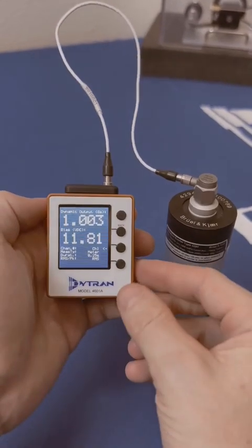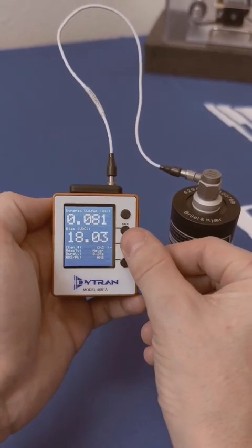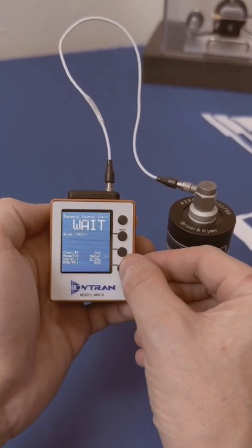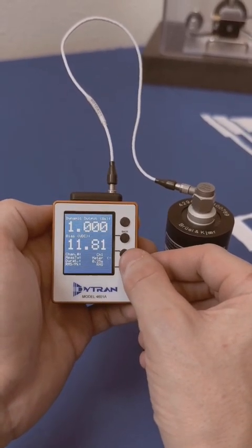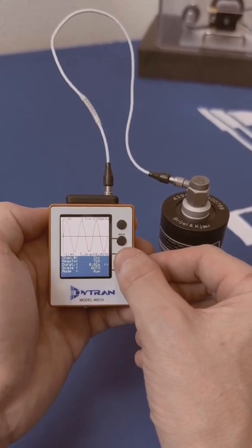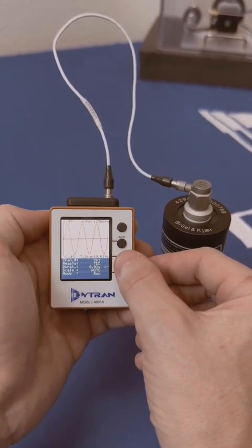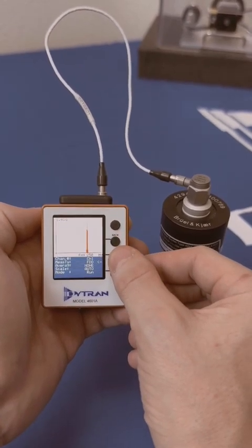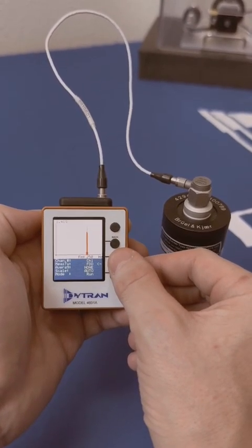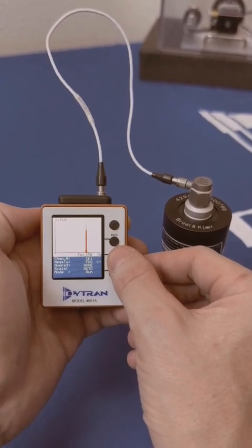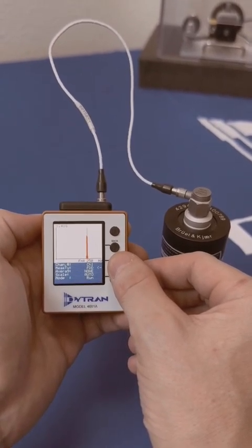If the live view mode is selected, the real-time data can be observed. The device operates in various modes: RMS or peak meter, which shows the current RMS or peak value of the signal along with the sensor bias voltage; time domain view, which shows the real-time sensor waveform; or frequency domain view, which shows the frequency content of the transducer output. The quick switch between channels, various duration, averaging options, and custom scales are available.